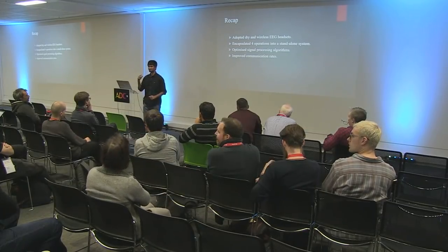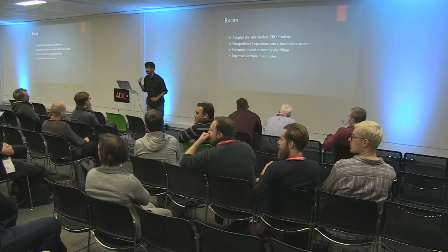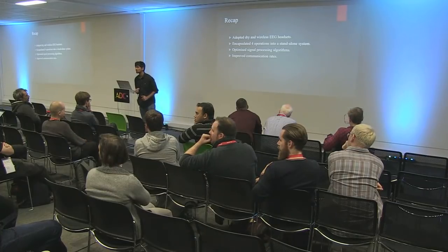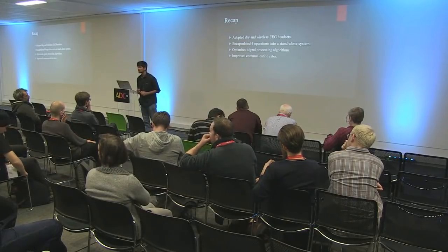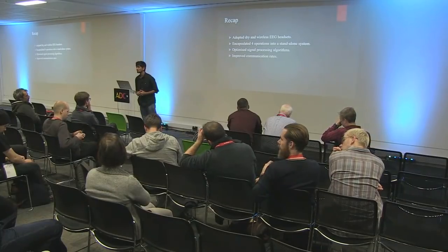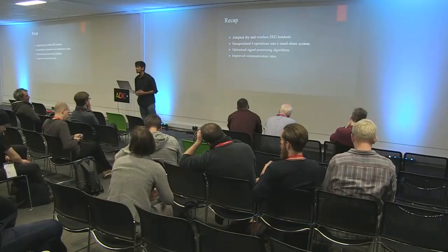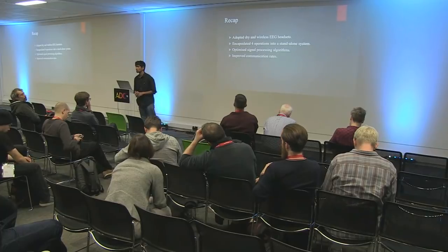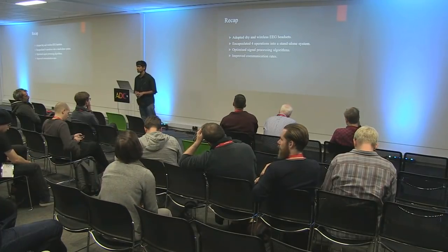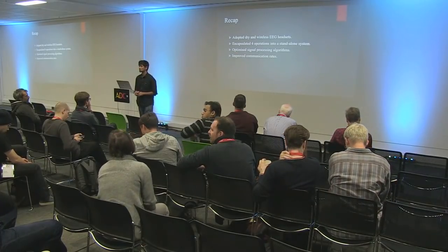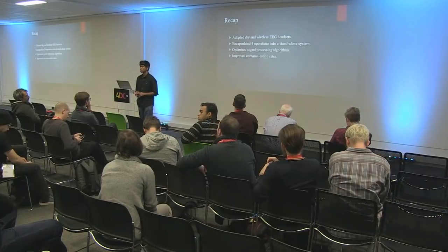Basically, I was asking whether the contamination of the signal could be because of the 50 Hz predominant resonance in the spectrum, and whether the 1 Hz could be due to the headset moving slightly, because in EMG, signals below 10 or 5 Hz are mostly because the device might have moved.